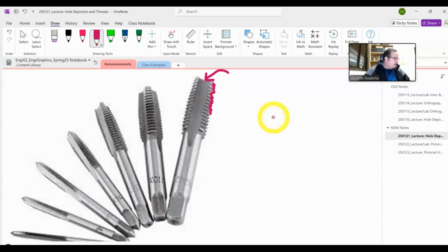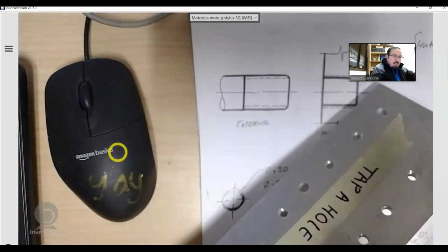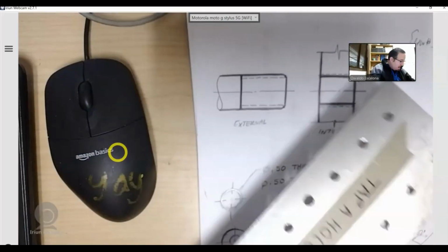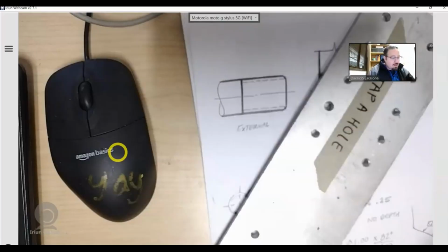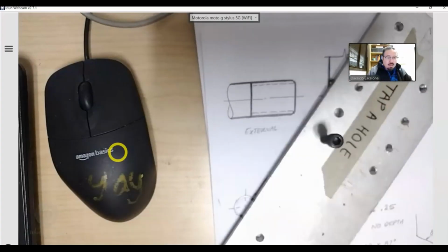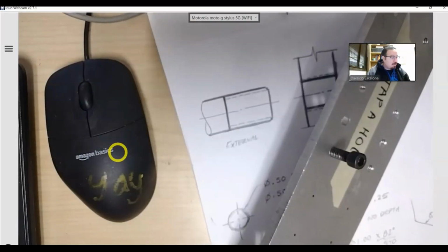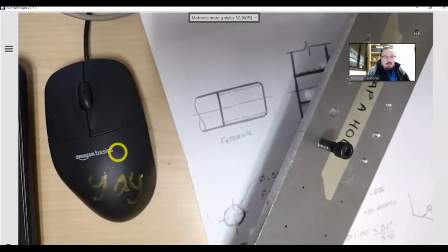So as you grab yourself the tapper, you put it in your chuck, which in my case is 100, so I will put it there. I grab the tapper, put it on top, and then I start. Once you get your tapper in, it's going to create the tabs, which are the internal threads. At this point, once it creates the internal threads, I'll be able to thread into my hole. Simple as that. You just get yourself a drill, a tapper, put the tapper inside of the hole, and boom, done.